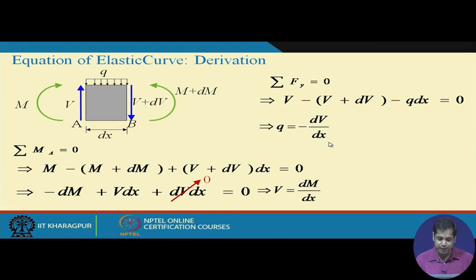It is just the brief review of the equation of elastic curve. You might have derived this expression in strength of material course or mechanics course. Now this is very important. If you remember, when we are drawing bending moment and shear force diagram, we observe that the bending moment is always one order higher than the shear force, and this expression explains that.